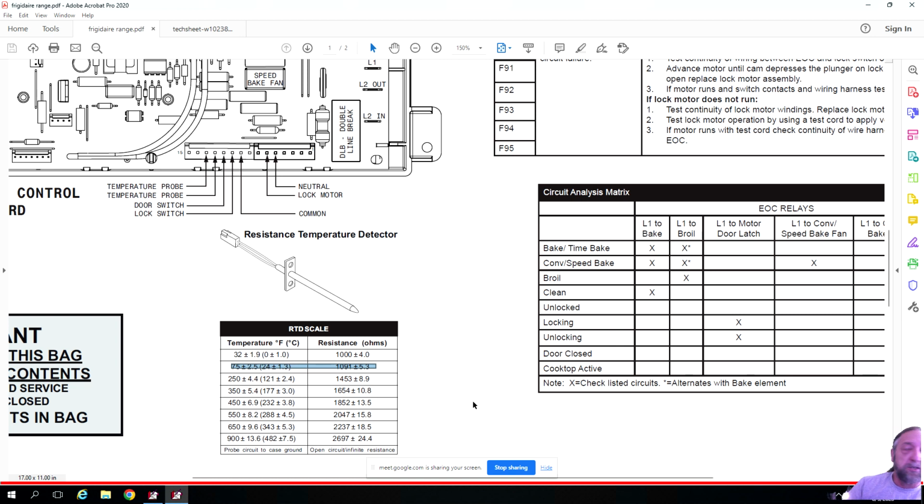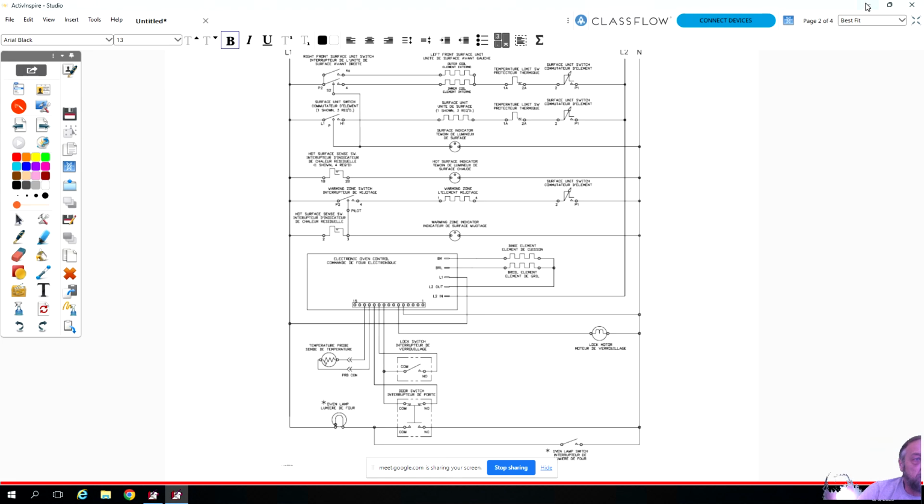Just to let you know, Frigidaire did some training at my school about 3 months back, and I was told the resistance values have changed. They've actually gone up to almost 2,000 or 3,000 ohms now. So don't get in the habit of knowing, oh, well, at room temperature it's 1050, this is what it should read. Make sure you go to the legend and check, because I was told the new oven sensors inside Frigidaire stoves have changed the resistance values. But the legend is important,